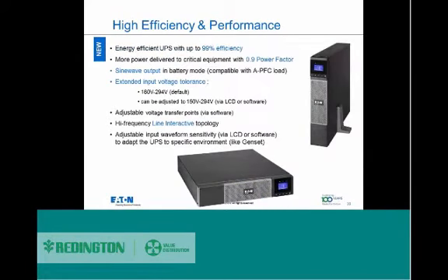These 5PX models are 99% efficient. They also give you a 0.9 power factor when connected to all their load equipment. Very rarely will you see such a power factor given by the competition out there, especially with this being a line interactive topology based UPS.